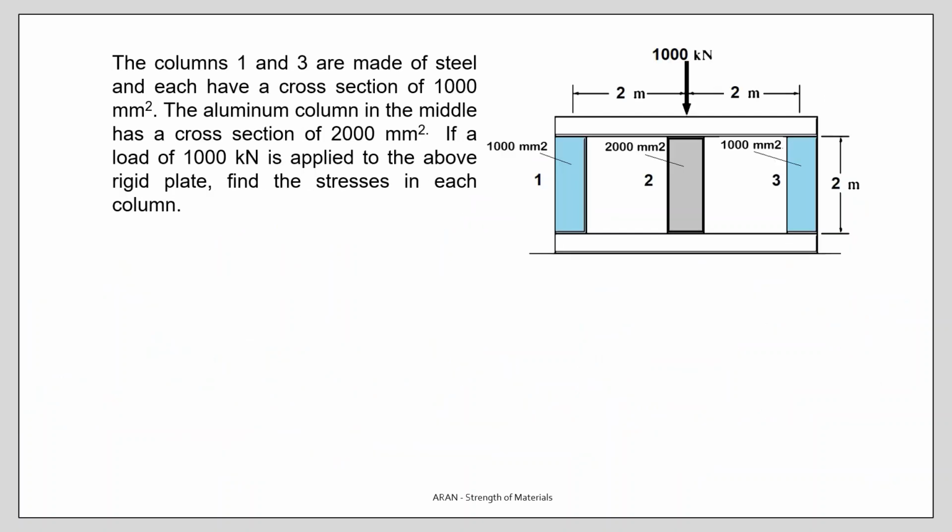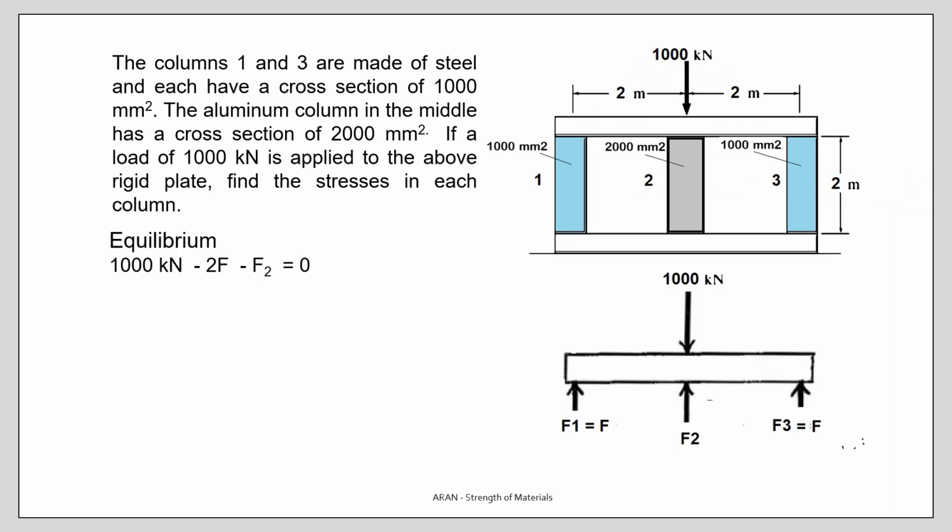Another problem. We have columns 1, 2, 3, all the same length, and we have a rigid plate, and we apply 1000 kilonewtons to this rigid plate, and we have to determine the stresses in these columns. The first thing I do is draw a free body diagram of the rigid plate, which is rigid, meaning it will not deform.